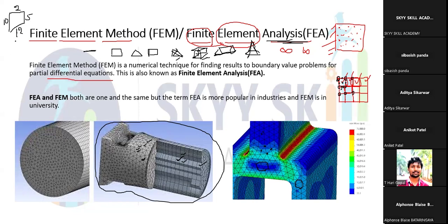Here I have to take the maximum edge length of the element, because as I'm having a quad element, this quad is going to have four sides. Among them, one side is going to be your bigger one and another one is going to be your smaller one. So here I am taking your bigger one, that is your 12, and smaller one, that is 2. So here what I'm going to get? Now 6. So this is a bad quality element, because when I'm getting aspect ratio as 1, that is the best quality element, or that is the ideal element.